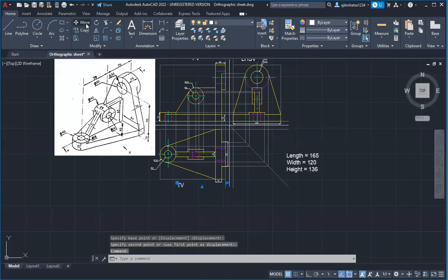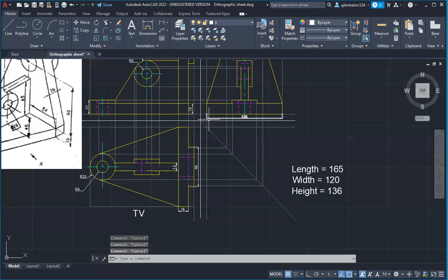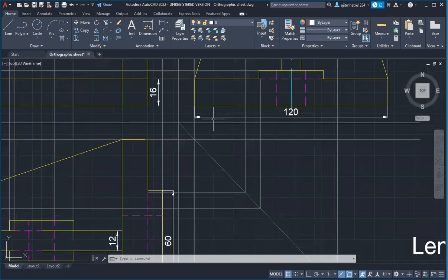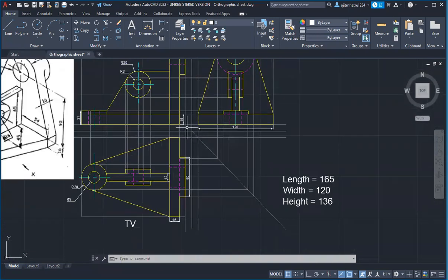So basically what you are trying to do here is placing the dimensions properly. You can make an inclined line. That inclined line is at an angle of 45 degree. How do you make it? Just keep in mind that this point you have to connect with this point. The center point of the box should connect with this end point, diagonally. Once you have connected it, simply extend it. Automatically the angle is 45 degree only because this is a square.